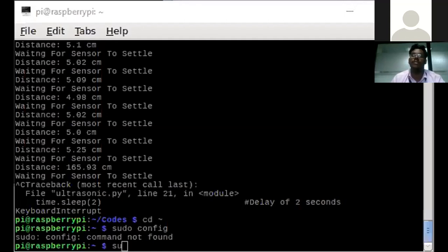In a fingerprint sensor, each fingerprint is stored with some ID. Whenever that fingerprint is read, it gets cross verified and that number is stored for attendance purposes. The humidity sensor is used to find both temperature and humidity in the environment, not in soil. We can interface it, and it has a DHT11 library. Based on the library, we can add it.